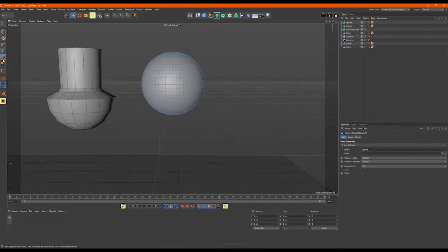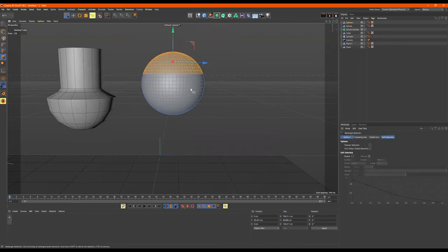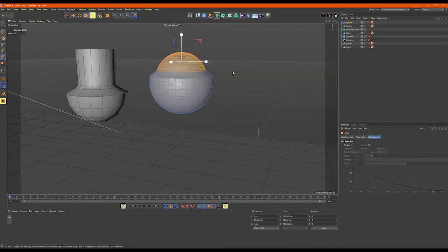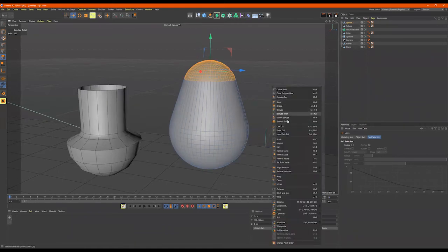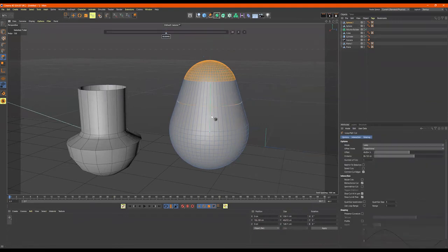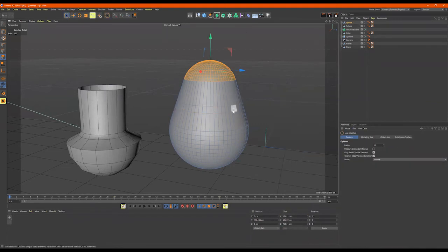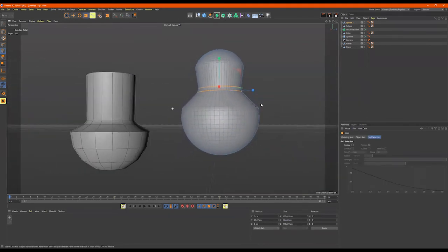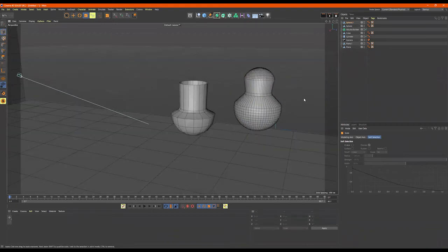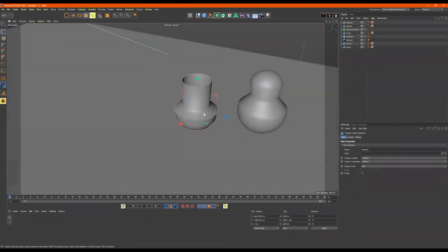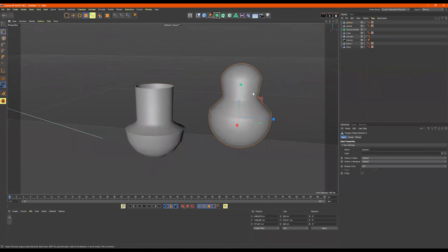C to make it editable. Go get these faces, rectangle selection. I'll select about half of these faces and I'll do the same thing. T to scale it in. Raise it up a bit. Right click. Loop path cut. Click, click. 9 to quit. Edges. UL. Shift. T to scale. So you have this right here. So if I type in NA, you can see this one looks a lot smoother and this one looks a bit jagged. Oh, let me delete the top as well. NB.